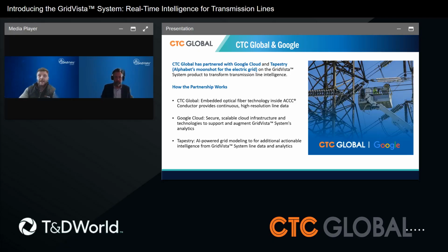Oh, that's a great question. The biggest benefit is direct observability instead of making assumptions. Single point sensors tell you what's happening at a few locations and force you to infer the rest of the line. Continuous distributed sensing lets you directly observe how the entire line is actually behaving, span by span and over time. That means localized issues don't get averaged away, emerging risks can be detected earlier, and utilities can operate and plan based on measured reality, not conservative estimates driven by sparse data.